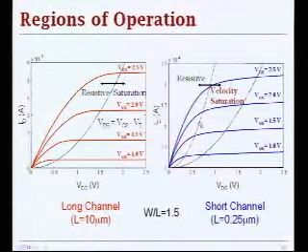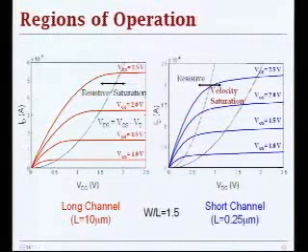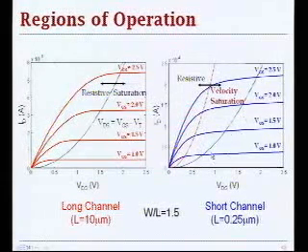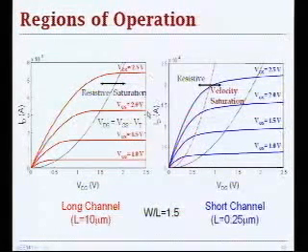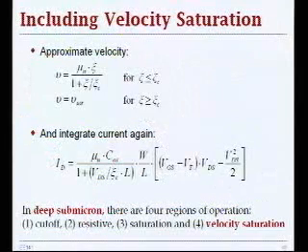Now let's see how we can model this phenomenon such that it's captured in the design equations that are important to us as circuit designers. So two things. You have velocity saturation that occurs much sooner than when regular saturation would have occurred, and you also have a linear instead of quadratic relationship with gate to source voltage for that reason.